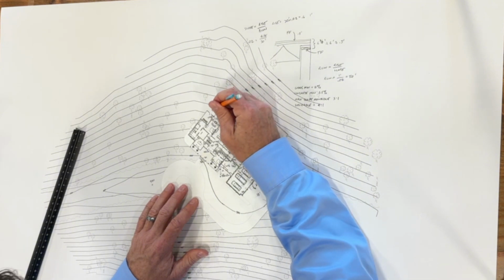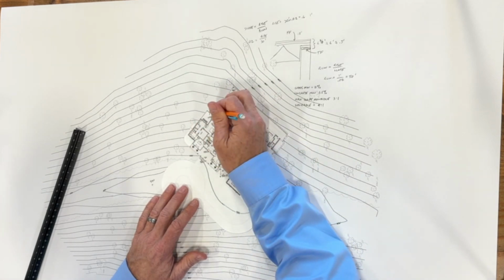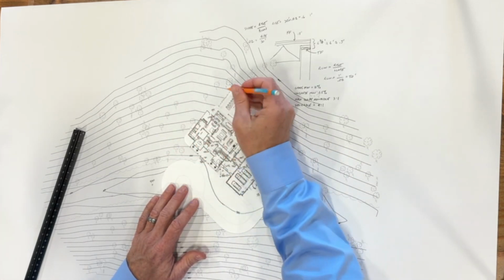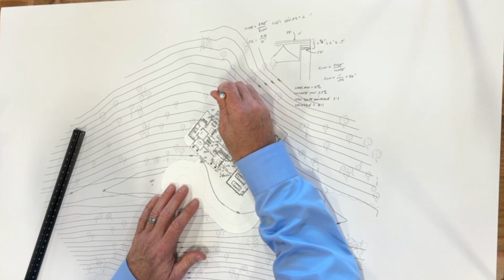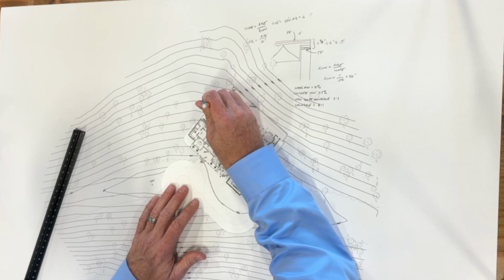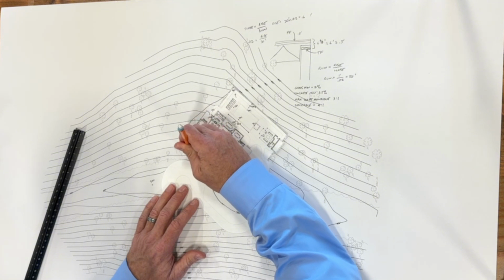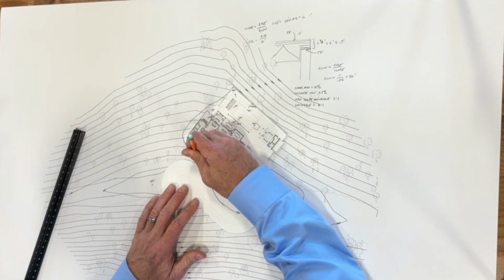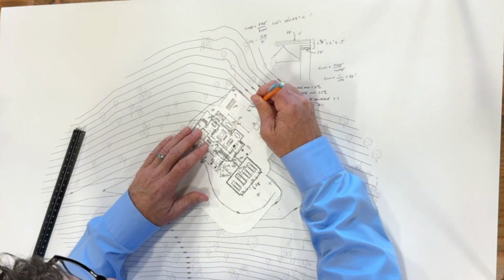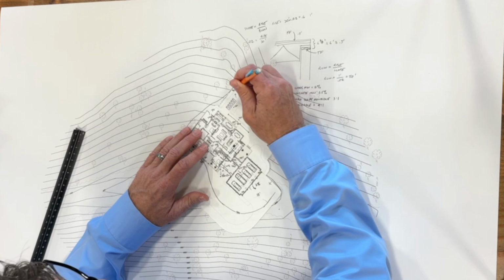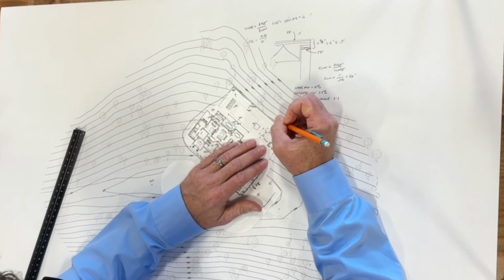Now we also know that we have 941 all the way over here, which means the 940 needs to be down the hill. And there we already know that corner is at 940, right? So I'm going to bring that 940 line here, and I'm just going to bring that around. And I don't know if this is going to work or not, but we'll just see what happens. So there's 940. So right now the 940 goes into the wall. And because that's a 941 to a 940.5, the 940 is in that wall. Comes off.